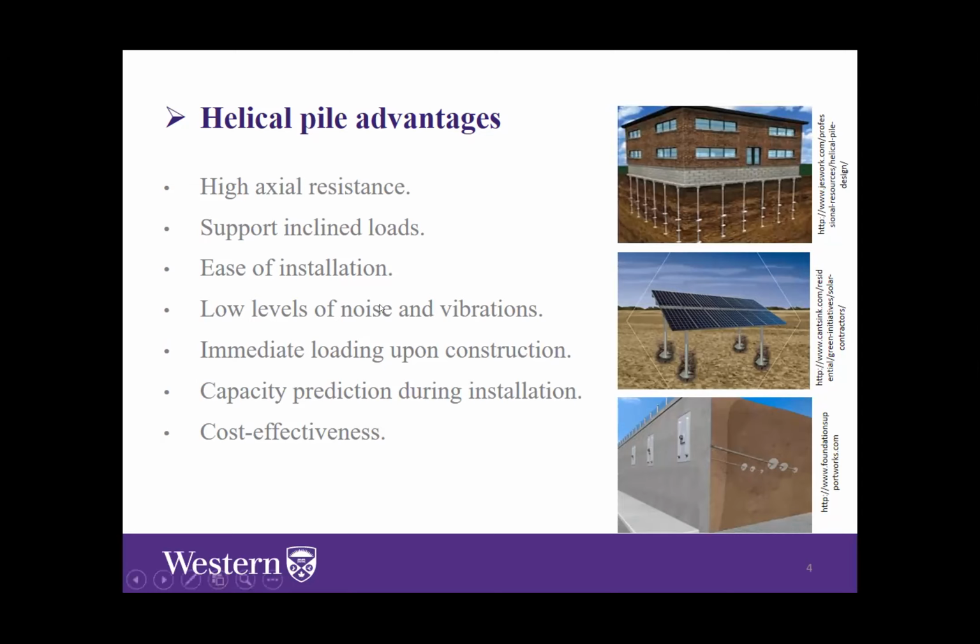It also provides a kind of quality assurance, because when we measure the installation torque, we can use some capacity-to-torque correlations. So you can expect your pile capacity once you install it without the need to do a pile load test, just by monitoring the installation torque at these depths, and then using some correlations to correlate this installation torque with the pile capacity. And the other thing, it is also very cost effective.